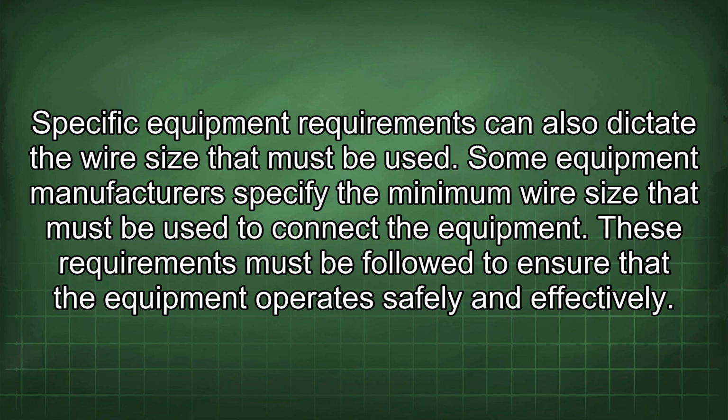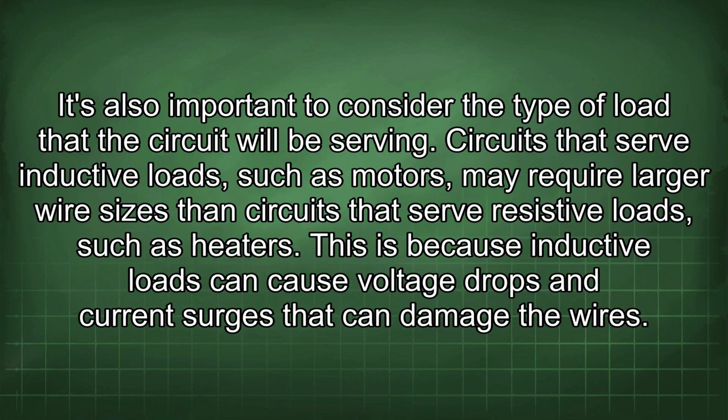Some equipment manufacturers specify the minimum wire size that must be used to connect the equipment. These requirements must be followed to ensure that the equipment operates safely and effectively. It's also important to consider the type of load that the circuit will be serving. Circuits that serve inductive loads, such as motors, may require larger wire sizes than circuits that serve resistive loads, such as heaters. This is because inductive loads can cause voltage drops and current surges that can damage the wires.